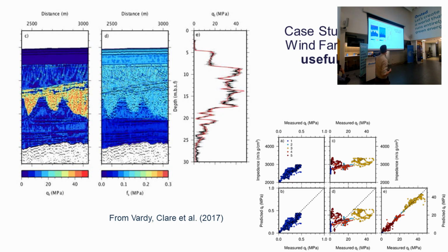And shown here in black is the predicted CPT trace. You can make out, hopefully, a little grey window either side of this. So this is based on 100 runs through the inversion. And then the red squiggly line is the actual CPT at that location.